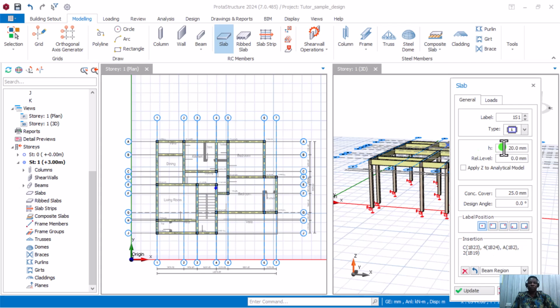We can just run it at 200, so that we'll have a 200 thickness, because maybe some area will need some pipe and some other area will be different. But in another scenario, we can look at how we can design differently. Maybe for this area, let's just design it differently. Then for this other area, we're going to put 150 where we don't have the slab.